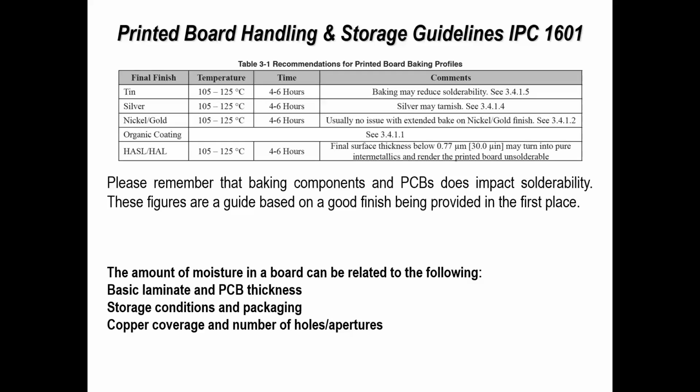Now, most components today are tin finish, or they are solder balls, solder spheres, which are either high temperature or low temperature balls, but it will have some effect. And I'll show you a couple of little tricks that you can use to evaluate this. So the point I'm trying to make here is that, yes, you can bake out, you can bring the board back so there's a limited amount of moisture in it. It will have an effect on solderability. Certain finishes are more prone to solderability issues than others, but you just have to understand what you're doing and why you're doing it.